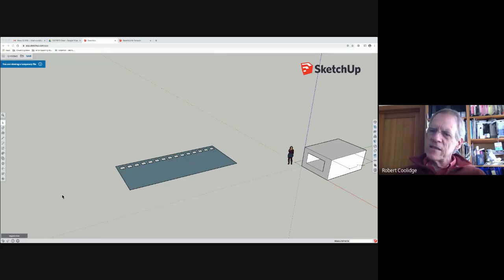And I think it's just to try and keep the user from making unmanageably small things, because it was originally created for architects. So that guy, Dave Richards, he came up with a solution. What he says is you draw your stuff like 10 or 100 times the size it actually is. And then SketchUp lets you make those tiny faces, and then you scale it back down again by that factor. And on the forums, that's become known as the Dave method because of him.